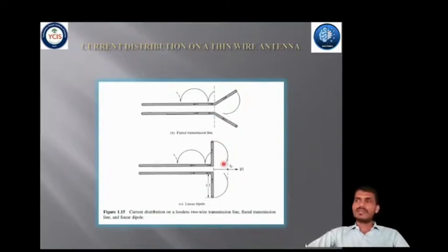In this figure, you can see that the fields radiated by the two arms of the dipole, which may be vertical parts of a flared transmission line, will primarily reinforce each other toward most directions of observation. Now the phase, due to the relative position of each small part of each arm, must also be included for a complete description of the radiation pattern formation.